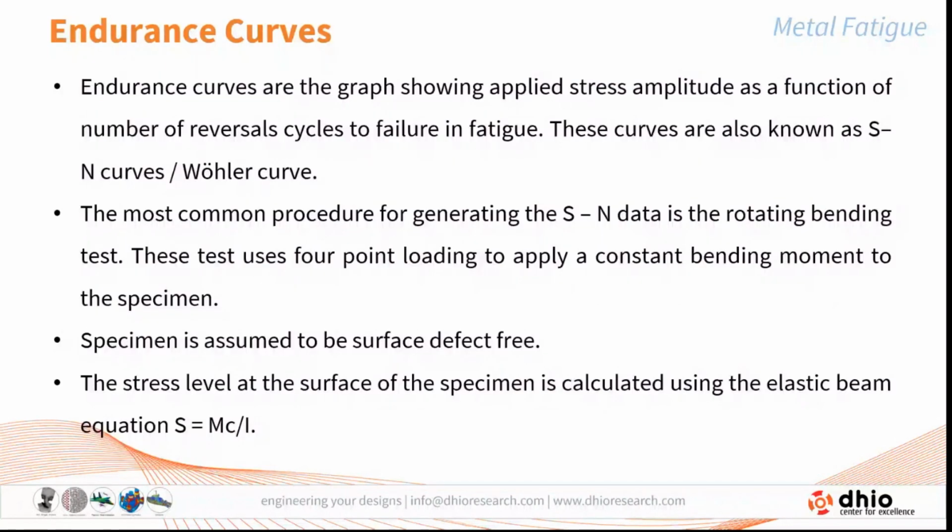And from this, one will get that when the members are loaded at different stress levels, how many cycles they can sustain. That is, what is important is the number of cycles which the material can sustain for a specified value of stress. So for every material, when it is subjected to a specific value of stress, you will get a specific number of cycles. Like that, when the member is subjected to different stress conditions, we get a different life of the member.